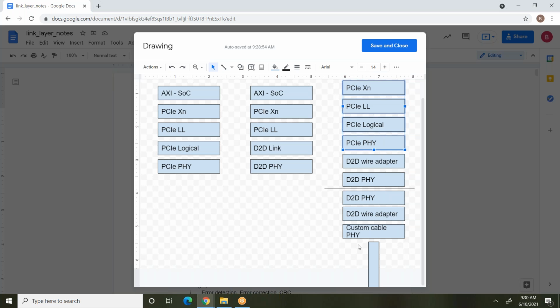Not only that, even if you ignore that, let's say you have DC coupling, because D2D PHY is not a single bit interface, it's a 16-bit interface, whereas PCIe is serial and maybe 16 lanes require them to be mapped to 16 lanes of D2D PHY. But the D2D PHY interface expects the data to be 16 times 16. So those kinds of logistic issues, even if we don't see electrical issues. Okay, so it's an unreasonable ask to have this wire adapter.